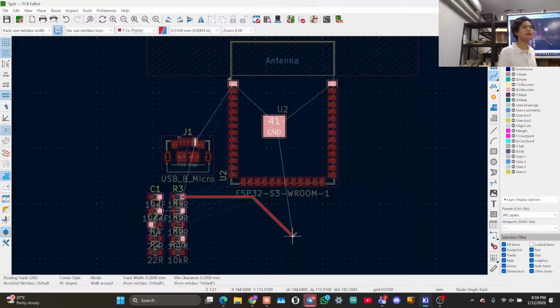KiCad is telling me, hey, all of these are potential places your trace might want to go. So you don't need to manually go and find. If you stare at it, that's highlighted. Just connect to that. It's more complicated than that for impedance reasons, but for just the purposes of wiring things together, just connect all the highlighted stuff together. So you can just not care about impedance.